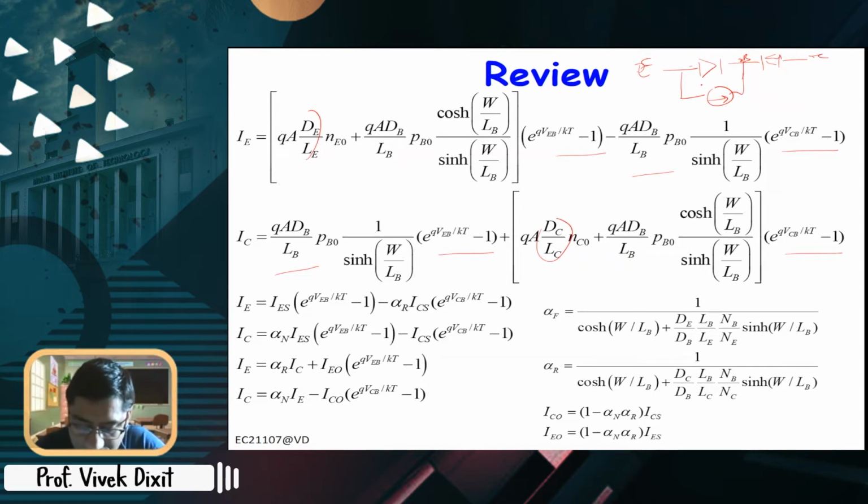So this is diode IES, and this is ICS. IES, this diode, this alpha ICS, so the opposite, right, minus, and then IC is basically moving out, so diode sign is opposite, so you will get a negative sign here, and this will be alpha and IES. So this is IES, alpha and IES. This is ICS, alpha R ICS. So you can recall this model.